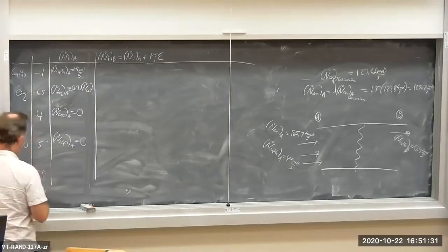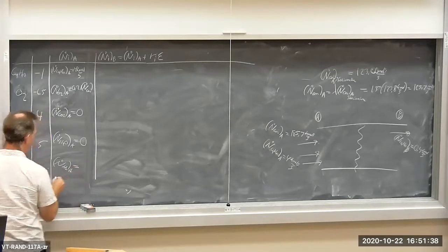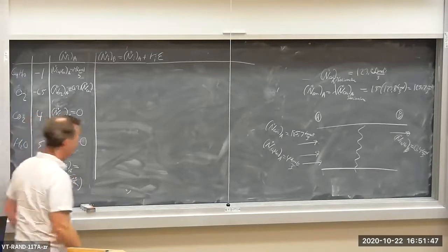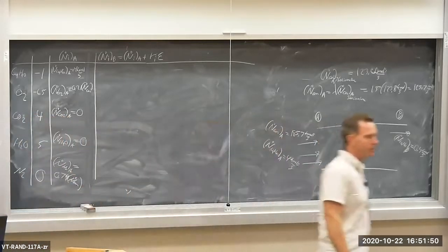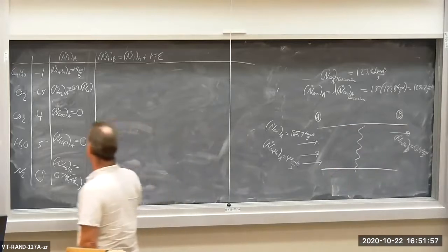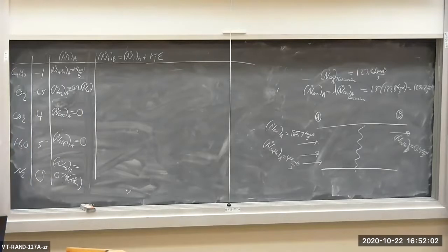And then n dot for N2 on the reactant side is equal to the mole fraction of nitrogen times n dot air. 79% nitrogen, 21% oxygen. So the oxygen and nitrogen mole flow rates are their mole fractions in the air mixture times n dot air. And we'll get some numerical answers here hopefully pretty soon.